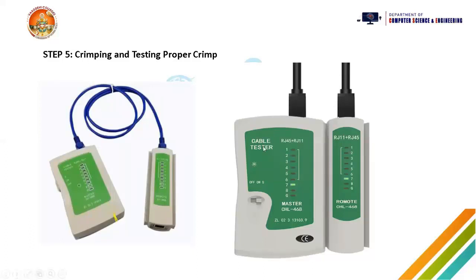For that, we have this crimping testing cable, or cable tester device, where we have to insert these wires from both ends. We crimp both ends similarly, then insert them and check if the lines of color lights are blinking properly for all 8. That indicates that the wire is properly crimped. If there is any problem, the lights will not glow, which means there is some problem in the cable, and then you have to cut the wire off the RJ45 pin and connect it to a new pin.